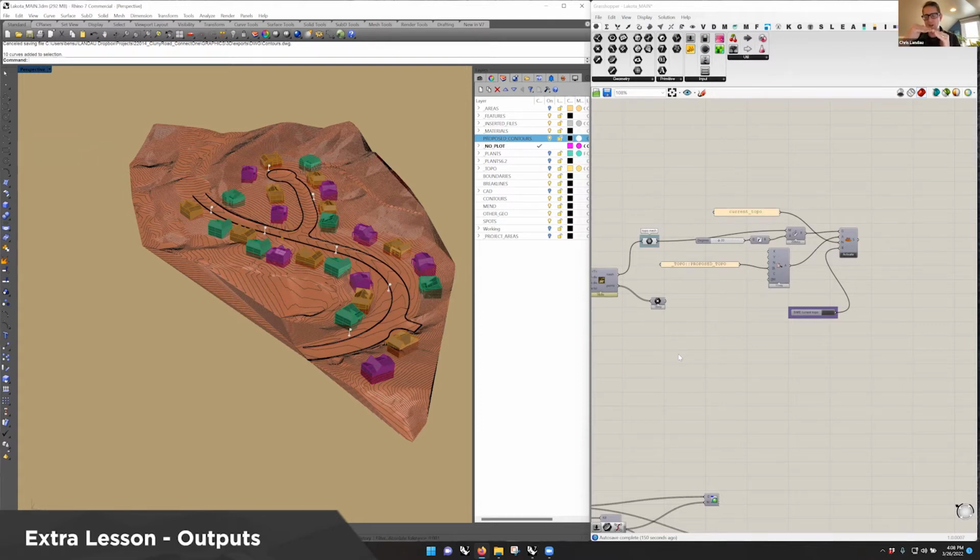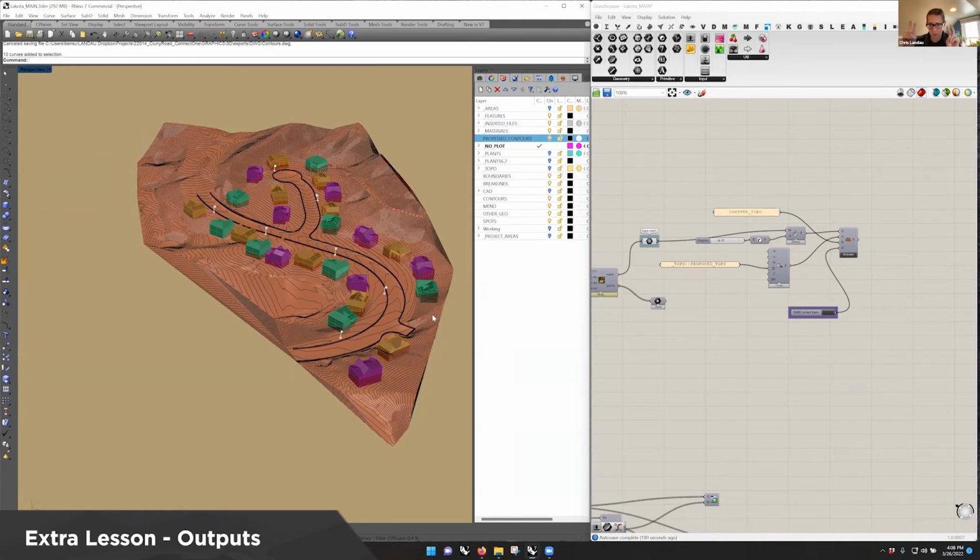One of the hacks that we've figured out is to take all the geometry from each layer, just take all the lawn, and turn that into a block in Rhino. And usually we just start a new file. If you turn all of that into a block and then go through the different material layers and turn them into blocks, you can export all the blocks at once to SketchUp. They're nicely organized then in SketchUp as components, which is what SketchUp calls them.